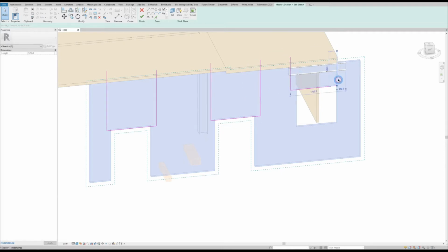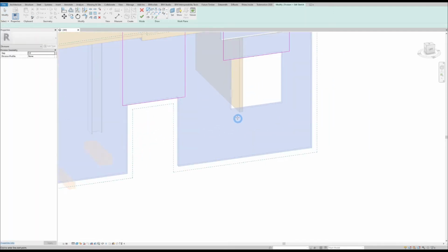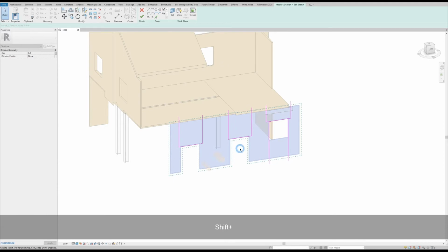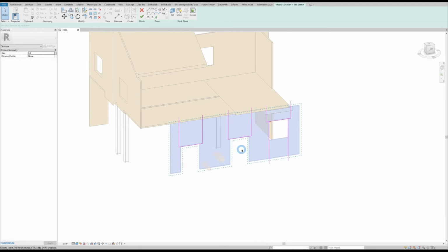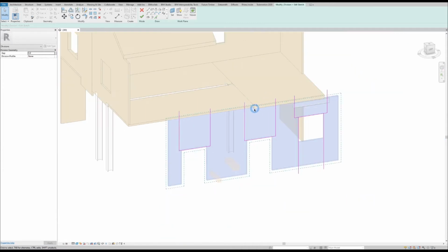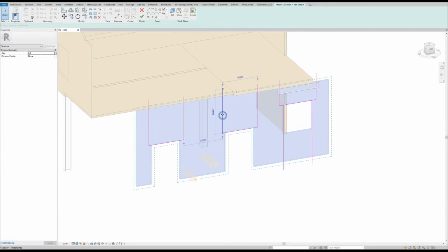And we'll just drag those ones. And we want to have a little sill seat panel over here. So we'll draw it like that. So the main thing to pay attention to here is these lines need to extend past this little dotted box. If they don't, then the part won't be split.